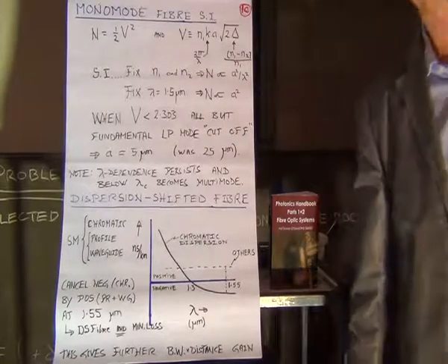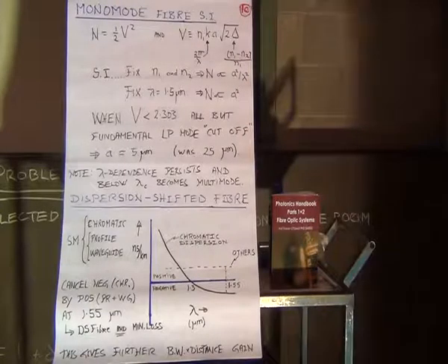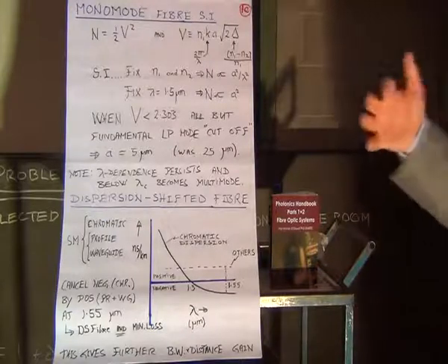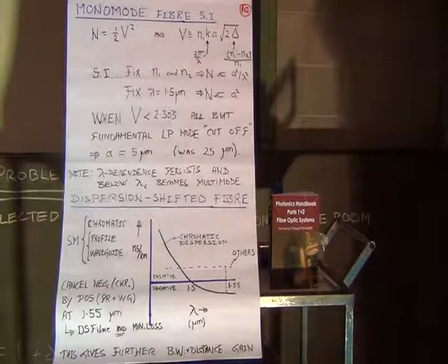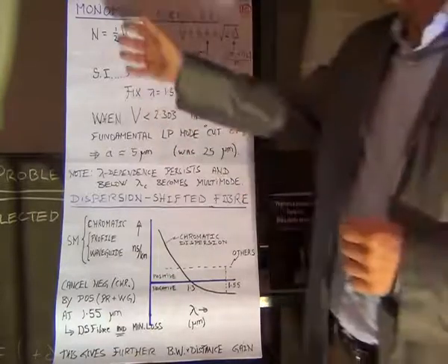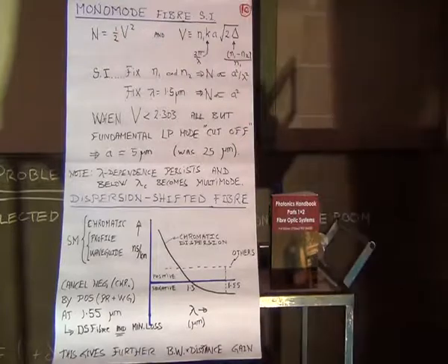That had huge alignment implications for mechanical engineers more than anything else, making connectors that align within a micron or less, and splice machines which splice 2 fibre reels together within less than a tenth of a micron perhaps. So the actual mechanical difficulties delayed the introduction of monomode fibre.